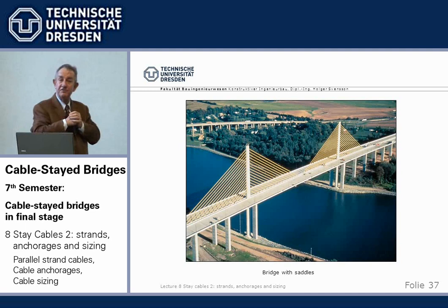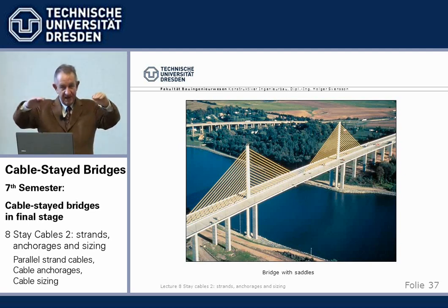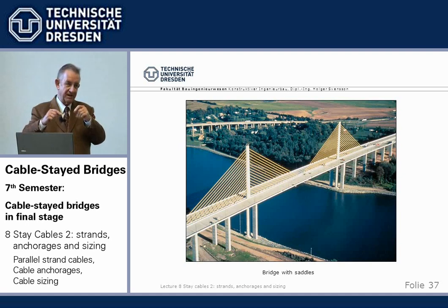What about the fatigue strength now in this clamped cable? With suspension bridges, we were not interested. There's a different situation with the stay cables. Well, there were first initial tests made, and they failed, and no good, and we were thinking about it. Finally, by making the ends curved, so that there is a gradient force increase in the saddle, and all sorts of tricks, people succeeded in getting the fatigue strength also for saddles, okay?